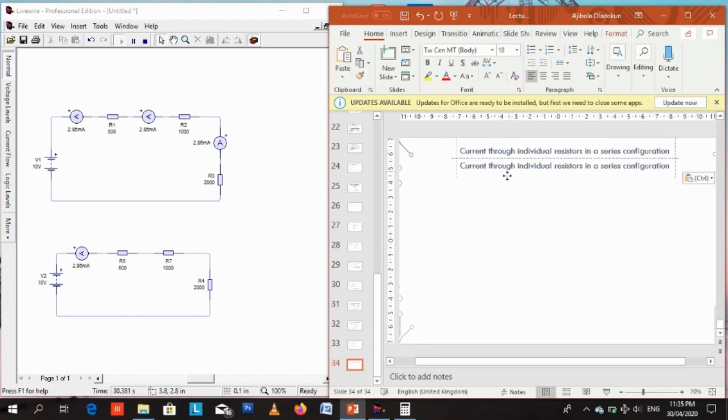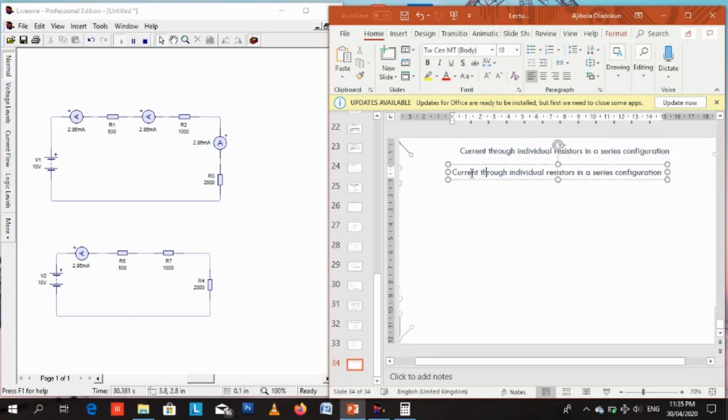If you want to measure current through resistors in series, just one ammeter will suffice, because the same current flows through resistors in series. So although the value dropped from 6.67 to about 2.86 something, the same current still flowed. If the value of the current drops, it will drop for everybody, for all the resistors in series.